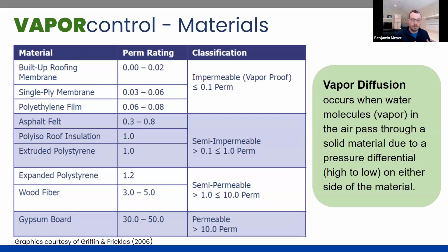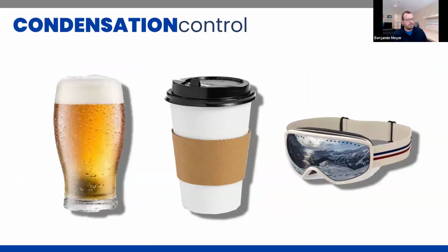There's WUFI modeling, there are best practices, but going through that again as the last step allows you to work through the specs and material properties without having to redesign the whole thing, the tail wagging the dog, if you will. Because most times when people are worried about vapor permeable or non-permeable, what they're really worried about is condensation. Am I creating a condensation risk?